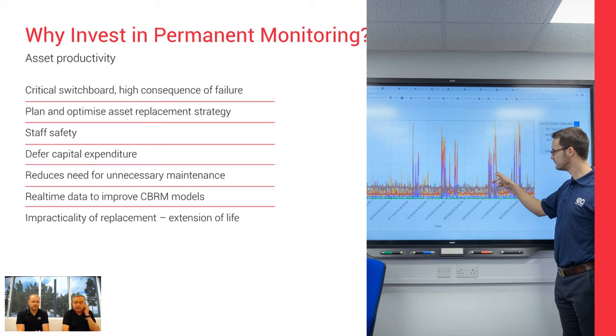Of course, staff safety. If you're working on one bus bar and you've got the other one live, people are in that switch room for an extended period. People put monitoring on the other half of the switchgear. If you're looking to extend the life of the asset, then deferring capital expenditure is another driver behind this.